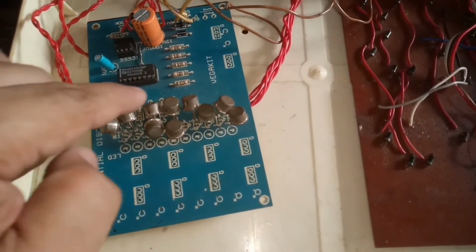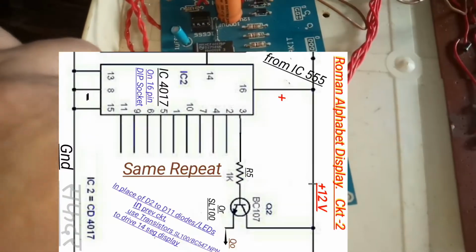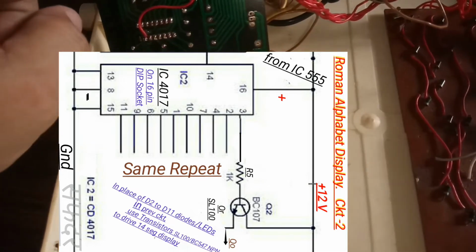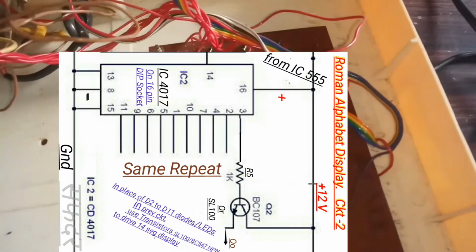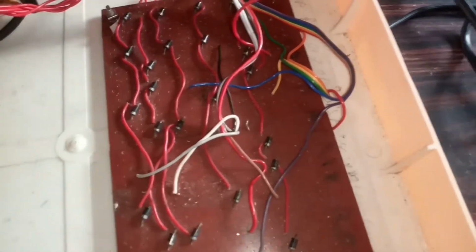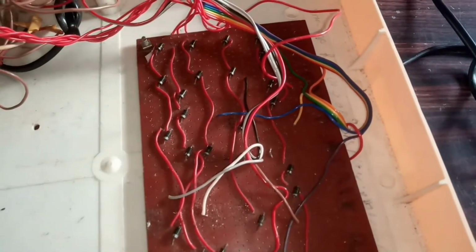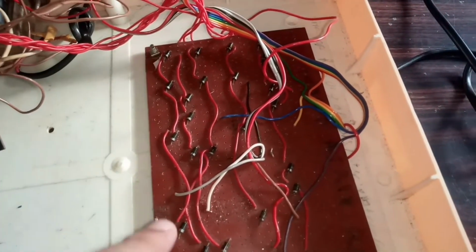Here you are seeing there are 10 transistors. Out of these 10 transistors, we are using only 6 transistors: 1, 2, 3, 4, 5, 6. These 6 transistors are connected to this diode matrix ROM circuit.